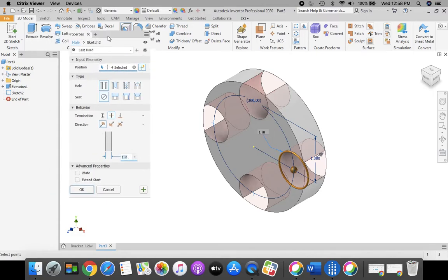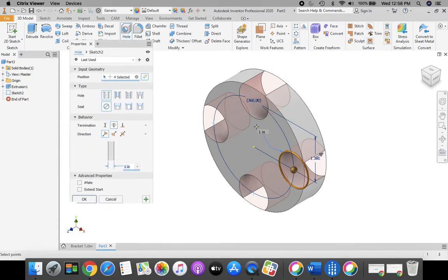And it looks like things went a little bonkers and weird because the holes are a giant size. However, it remembers the last diameter that I typed in. So let's go through this menu. We're going to leave this for now. Everything's okay. If your holes do not automatically select though, you may have to come over and click each one of your plus marks or point tools in order for those holes to select and pick up.